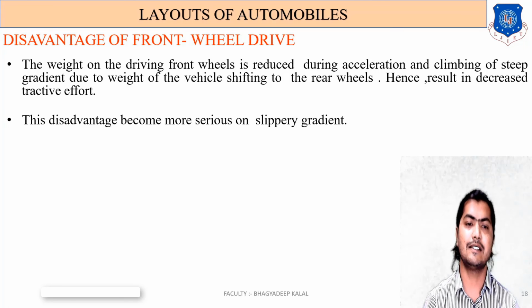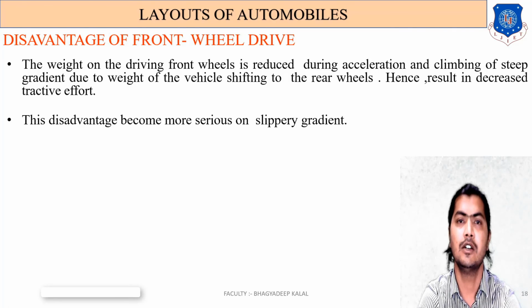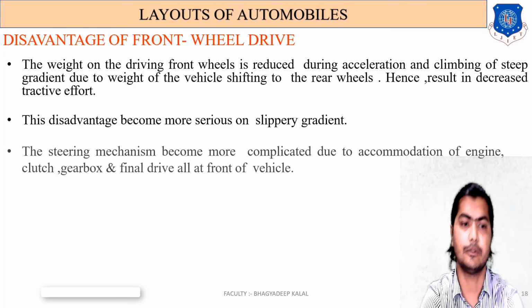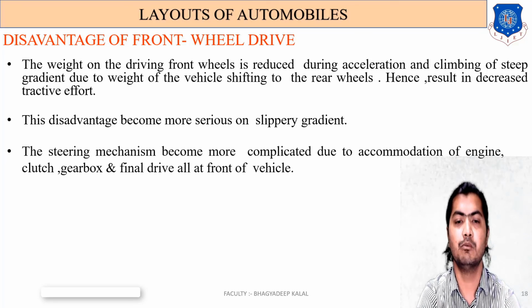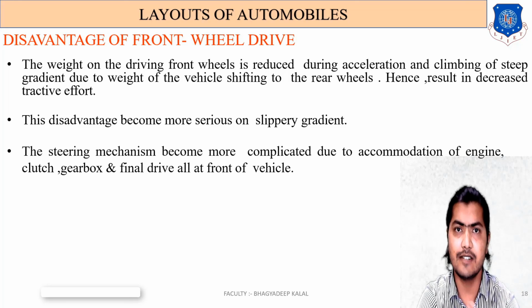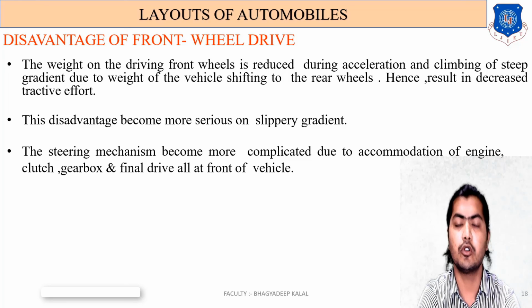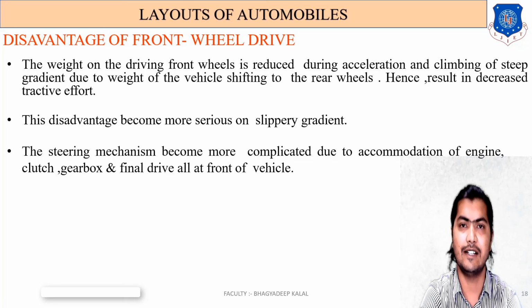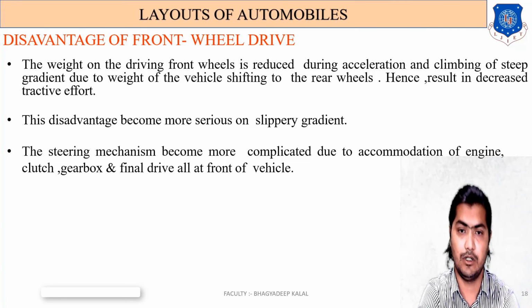Next, this disadvantage becomes more serious on a slippery gradient. Slippery means an oily or slippery surface. Also, the steering mechanism becomes more complicated due to accommodation of the engine, clutch, gearbox and final drive. All the components are fitted on the front side. At that time, the steering mechanism is mounted in a much more complicated way.